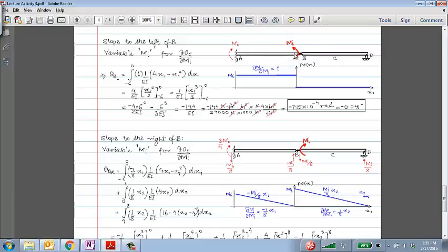Okay. So if you apply an additional moment to the left of the hinge, you should be able to see that this segment comes into a constant moment, Mi, and the right hand side there is no moment, right? If I take the derivative of that constant moment, I get 1. So similarly, I take 1 times the actual curvature. To find theta B on the left side, I take the derivative times the actual curvature, and the rest of this is just algebra.